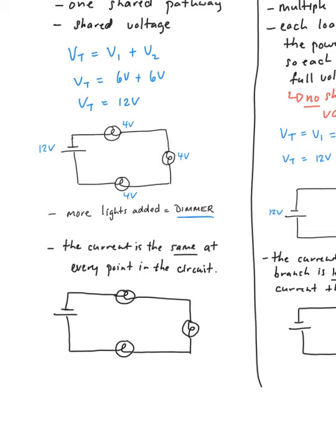And I would measure that using something called an ammeter. You actually need to put the ammeter into the circuit. So you can put an ammeter there, you could do it over here at a separate time, I can measure over here, and I could measure over here. It doesn't matter what part of the wire.